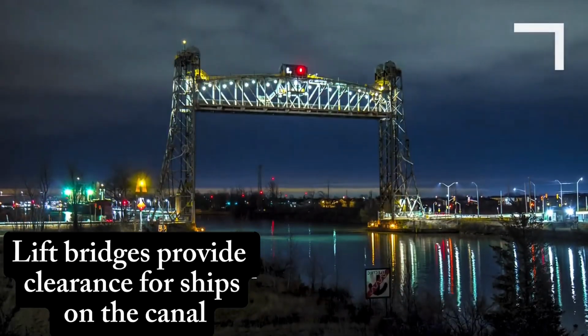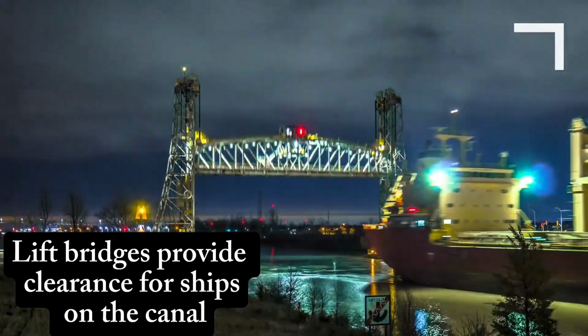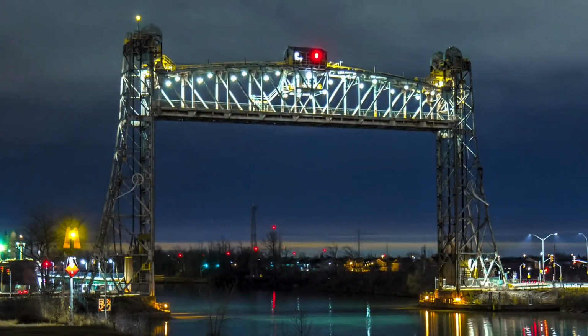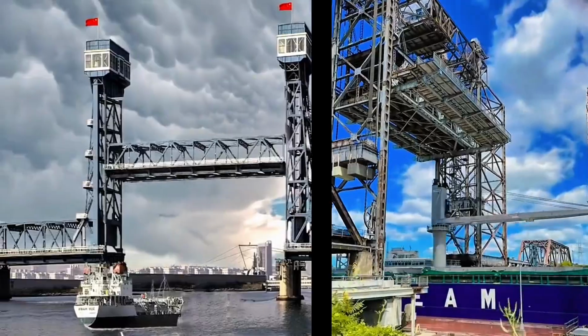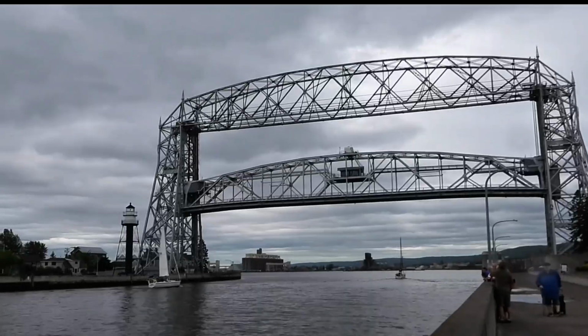Vertical lift bridge. A vertical lift bridge raises its entire span straight up between two tall towers using cables and counterweights. Unlike a bascule, which rotates, the vertical lift bridge moves vertically while remaining horizontal. This design allows large ships to pass beneath and is especially effective for wide waterways. Examples include the Arthur Kill Vertical Lift Bridge in New York.